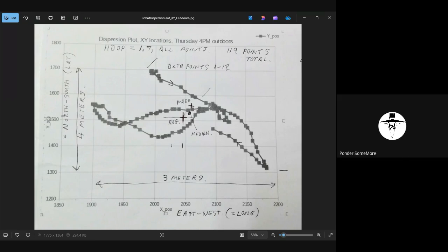I would say that there's a lot of confusion about that out there. Again, I don't consider myself an expert on this, but I've delved into it. The original indication I got was that you're going to get better accuracy, but the real truth is you're getting better reliability. What you are getting in terms of accuracy is a little bit better when you're near structures, but that's really more about preventing dropout of signals. So your signal quality does go up a little bit, but you're still going to get this random walk behavior.